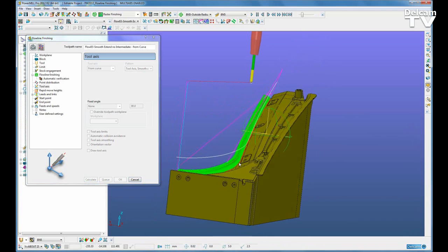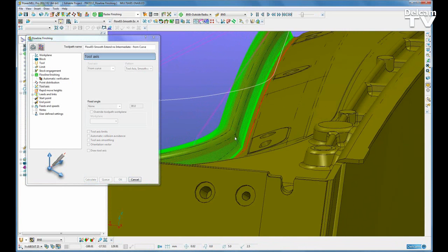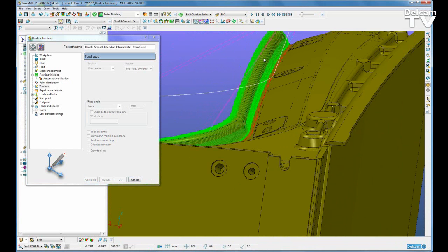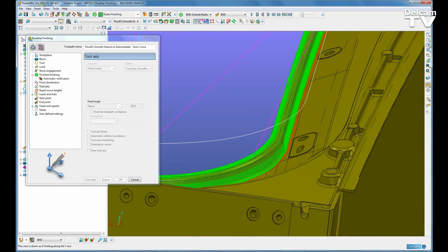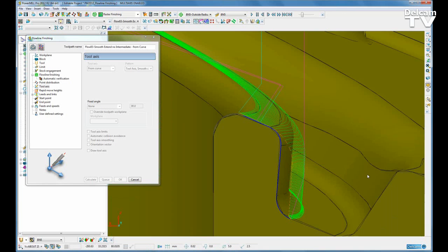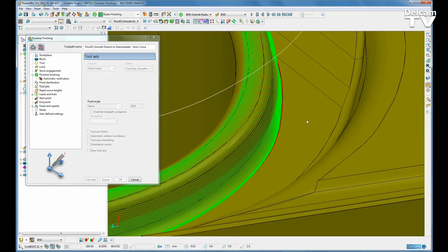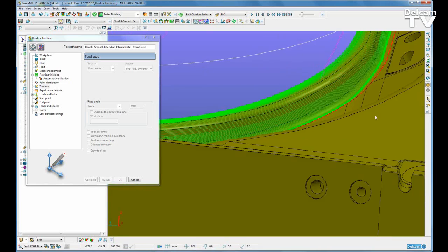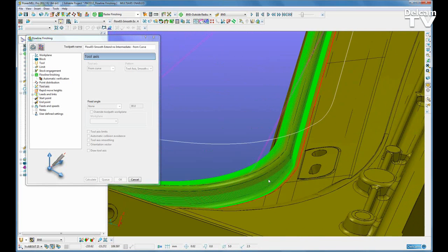Now, the flowline toolpath has been created, and we can see one toolpath has machined the top surface, the rad, and the sidewall all the way down to the fillet at the bottom. And also in so doing, it has machined the undercut side wall. When we look at this toolpath in here, we can see that while the results have been very, very good, we can still make out that some of the passes here are not following that capping rad, are going round.